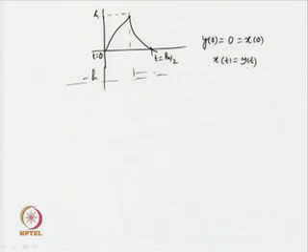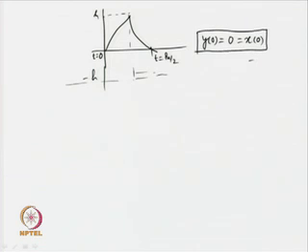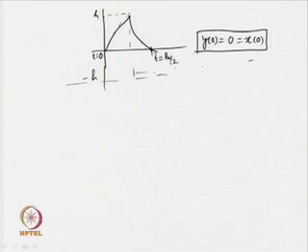So, for this first order plus dead time system, definitely it is true that x(0) = y(0), and that is also equal to 0. Further, for the limit cycle condition, we know that the positive half and the negative half are symmetrical. That means we have half wave symmetry and therefore, y(Pu/2) will be equal to minus y(0).